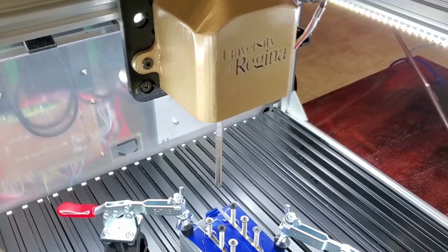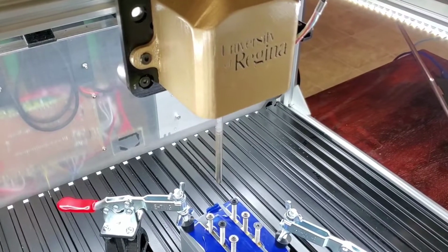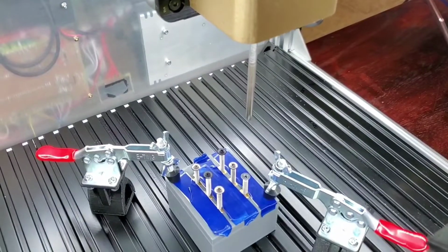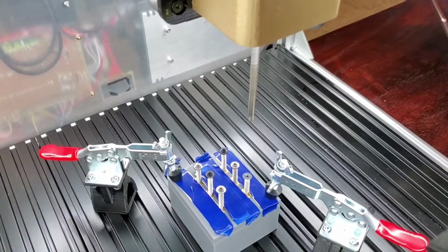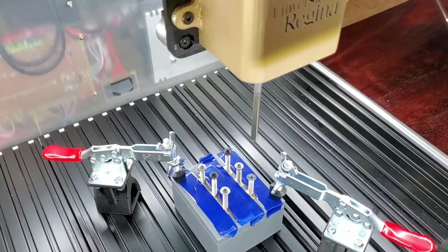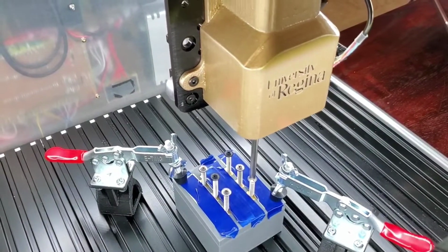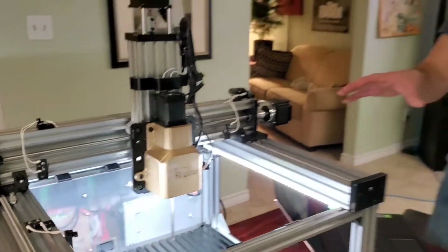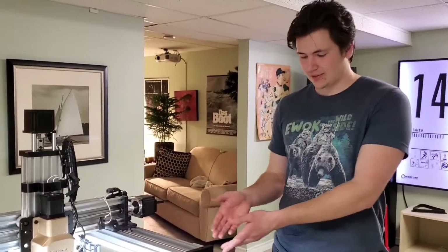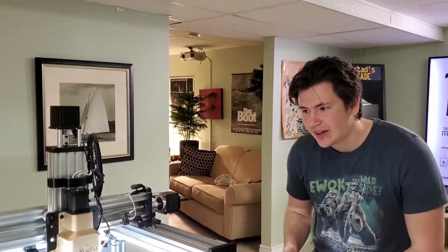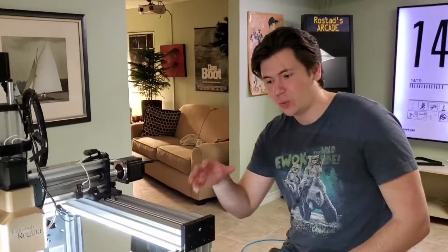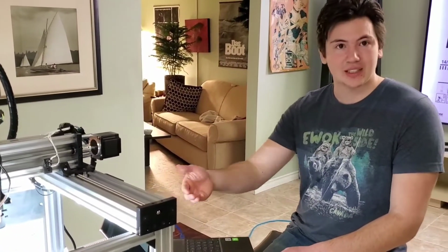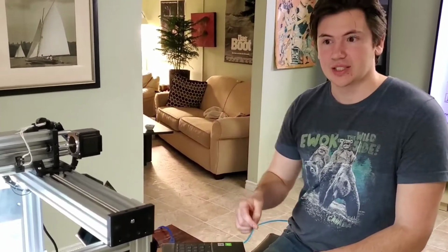Now this is the final screw here, so it's going to align with it. And again, take a zoomed photograph, line up the screwdriver with it, home the encoder, move down, rotate that screw. So now we've effectively tuned this filter to the requirements of what the tuning algorithm told us. Now, of course, in reality, you're not just going to do one quick tuning cycle, you might do another one. So it might send us another tuning file, and then it would repeat that whole process.